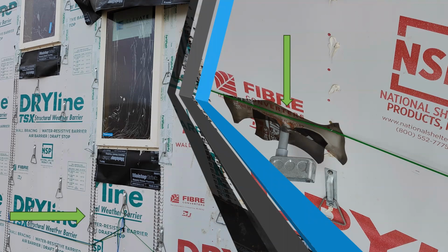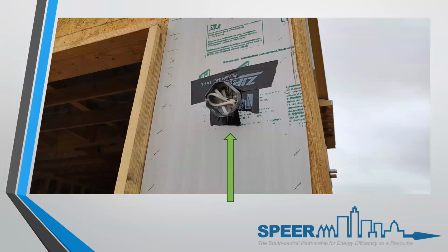There's some nails that you can see through there. Most of the time that alone is sealing up that. On the right, where the red T-ply is, you can see caulking being used over the nail heads. We've talked about that in previous presentations that we've done. Same builder that I walked before. This is also kind of the same thing of what they're doing.